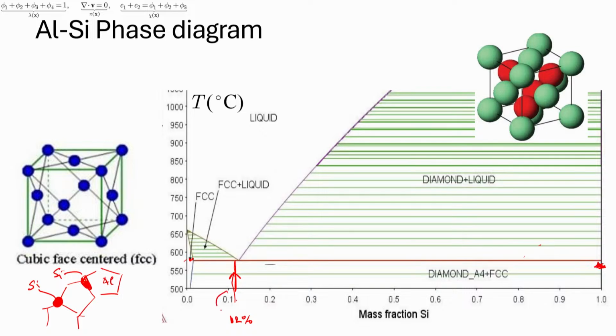At this nominal concentration, well, the lowest composition that will melt is the eutectic one, right? So as silicon diffuses, the first area to melt is the one near the interface, right? Now, if this melt percolates, so well, sooner or later it will percolate, and then you get a flow, right?